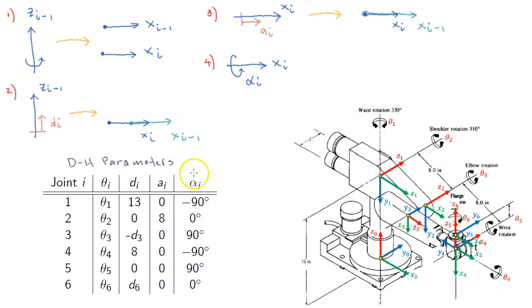All right, next, let's look at joint number 2. So this is coordinate frame 2. Let's see if we can do this without drawing. Okay, so first, we have to rotate coordinate frame 1 to make X1 and X2 pointing in the same direction. They are already pointing in the same direction, so we don't have to rotate.